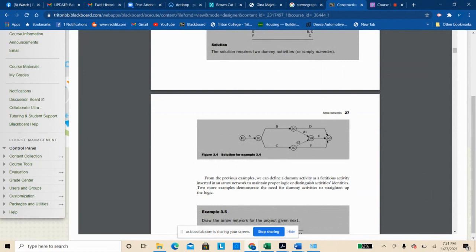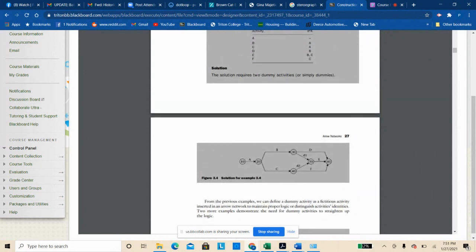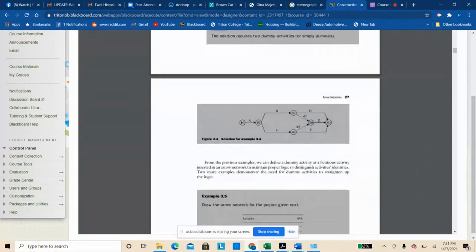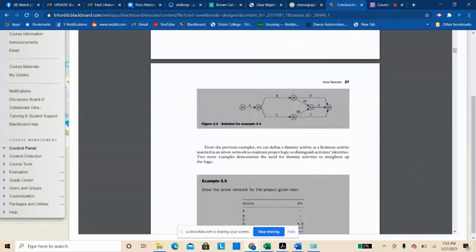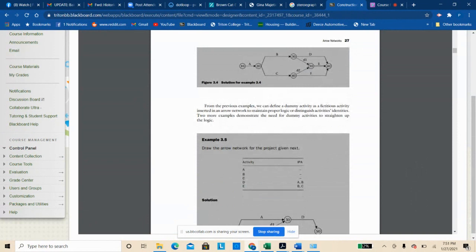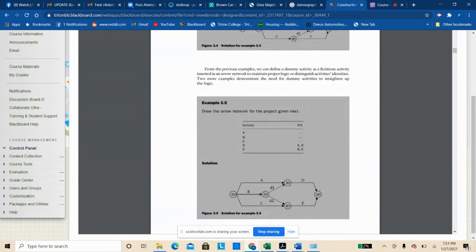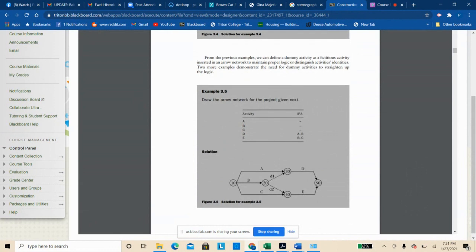Those 2 would be the same if we didn't have the dummy tasks 1 and 2, which then create the different task for E. It gets a little bit obscure, and I just want you guys to understand the concept behind it and be able to explain unique paths and identify between different paths for a construction project.